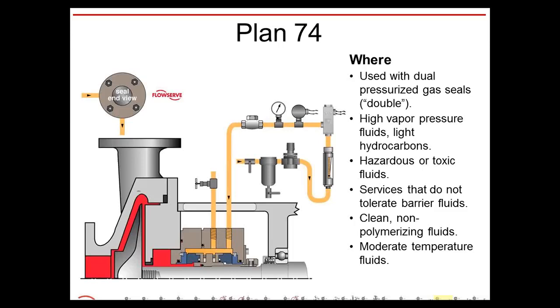It's not a compressor, but you have a very bad flash point. They also work for hazardous or toxic fluids, and of course any type of service that won't tolerate certain types of barrier fluids. If there are no fluids that are really compatible with what you're pumping, you'd have to use a gas seal.